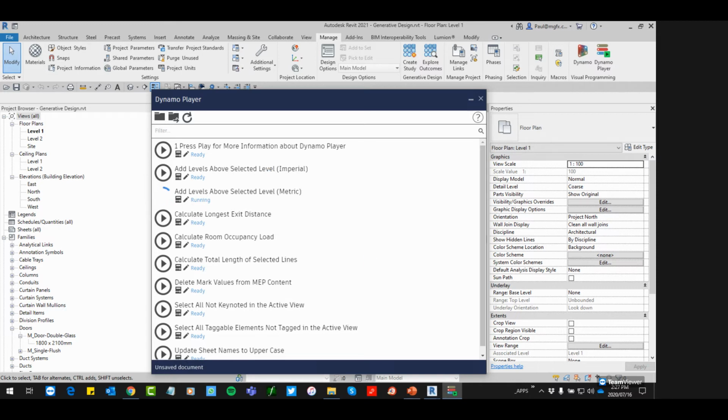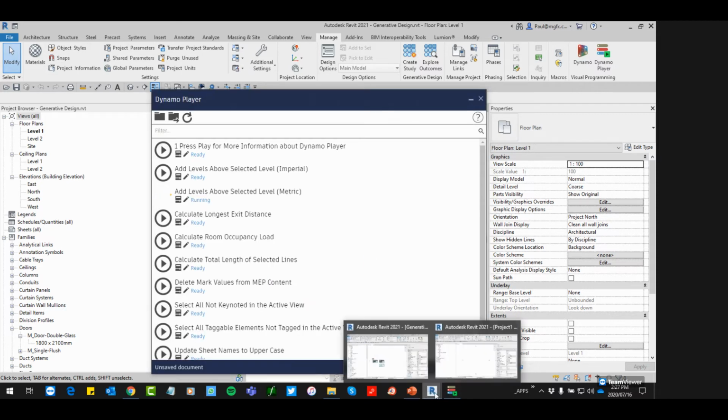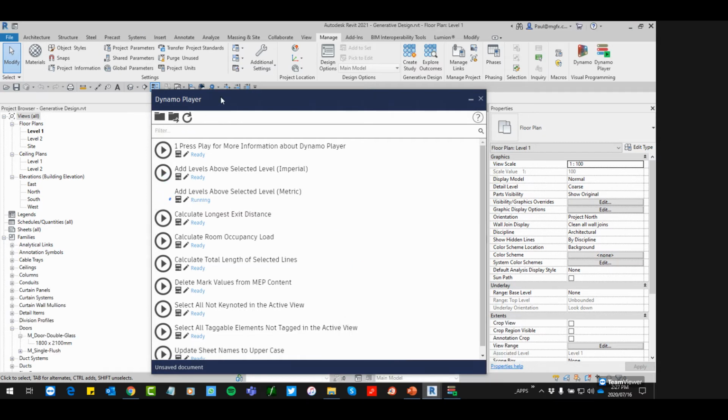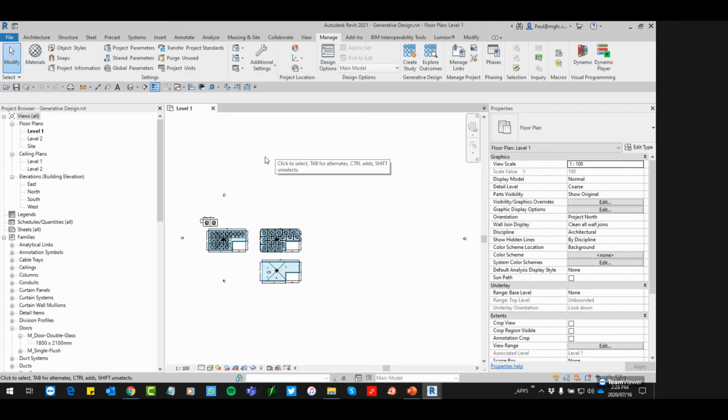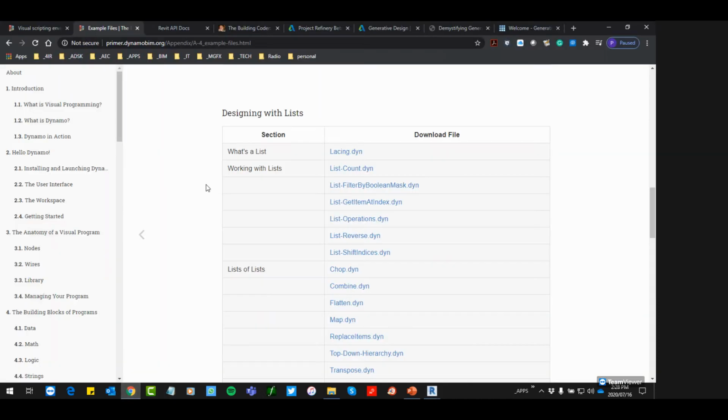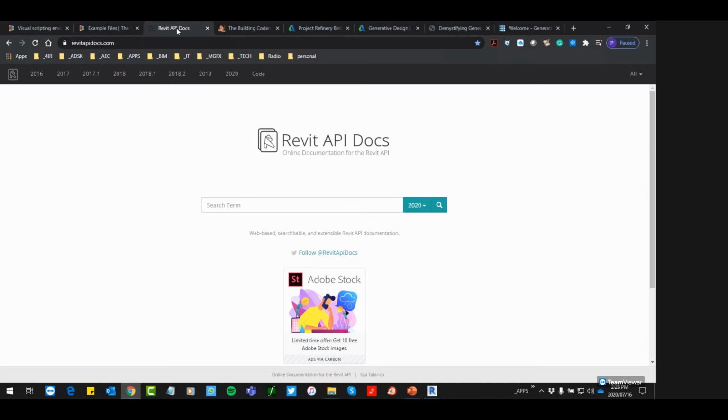And then we can see we can have some inputs into the script. And they would like to have some information that we can input. Right, so one does this within Dynamo in a specific way. One right clicks on the node and says add it as an input, and it will appear like this when we play that file. Pretty much the same thing within generative design. So when we ask a question, we need to ask the question using Dynamo. Then when we can't ask the question using Dynamo, we resort to the Revit API docs.